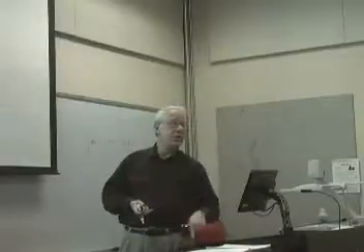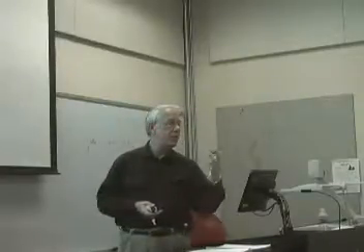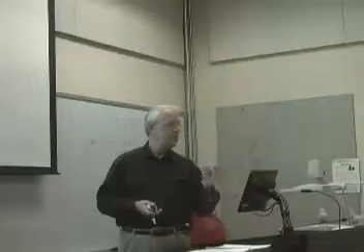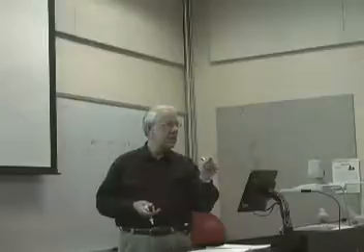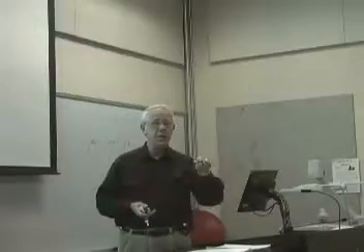The shape functions now for a triangle, you're using N1, N2, and N3. Why? Because it's 3 nodes. Each leg of the triangle consists of 2 nodes, correct? That's a linear leg. So you have 3 linear legs. That's all there is to it. So you now have shape functions for N1, N2, and N3. These are the relations for those shape functions.